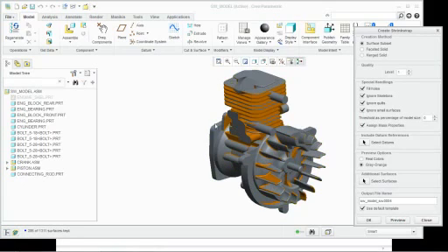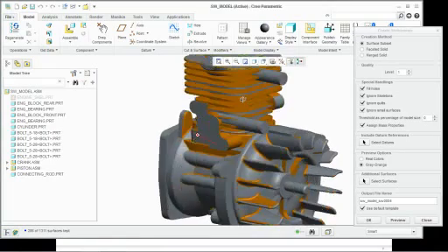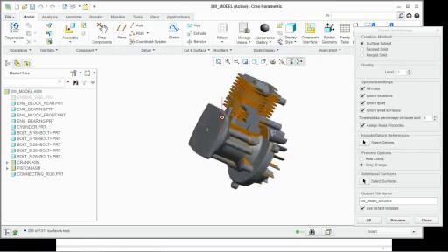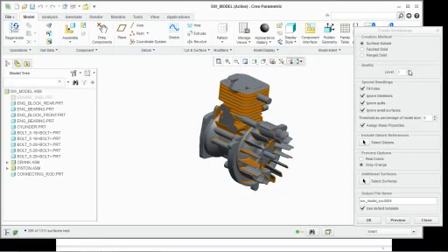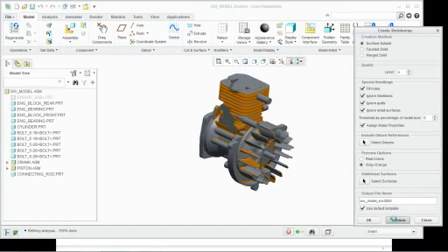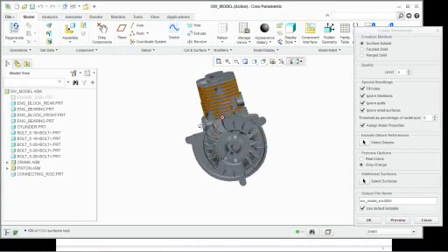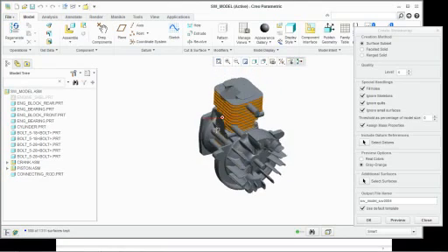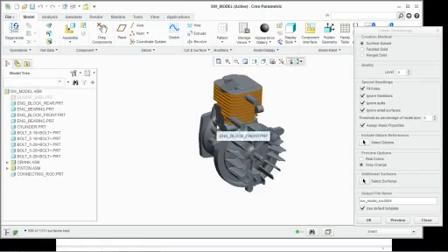Notice the orange surfaces are the ones that are going to be excluded. So if you notice, there's lots of surfaces here that are going to be excluded. So maybe I want to crank up my detail level just a little bit and say maybe I want this to be a level 4. Click OK. That's just an alert saying, hey, you're going to change some stuff here. Now if I click Preview again, notice that a lot of those orange surfaces have gone away. I still have some. Still going to exclude a lot of these, but my geometry is a little more accurate to what I want it to be.